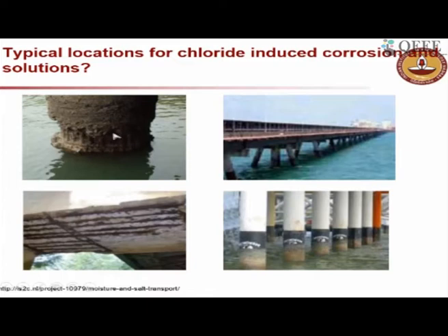You see much more corrosion there because that is a region where both oxygen and moisture are available in enough quantity, and it accelerates corrosion. Now here this is a bridge, and here is another bridge. This is the bottom view of this bridge, where you can see a significant amount of corrosion, on the bottom side where you have more moisture than on the top surface.